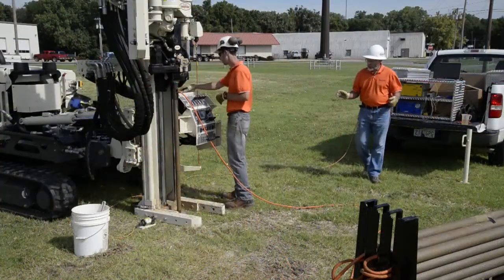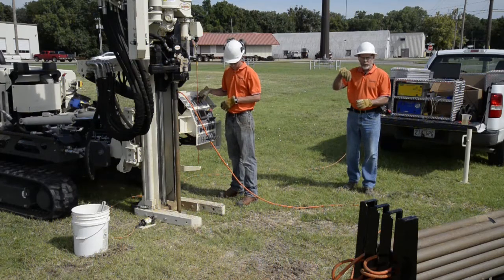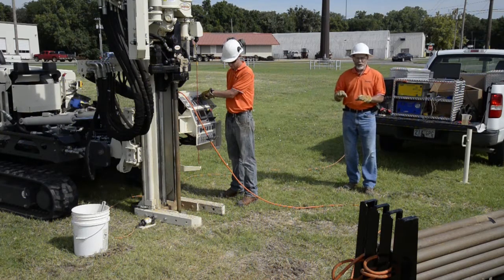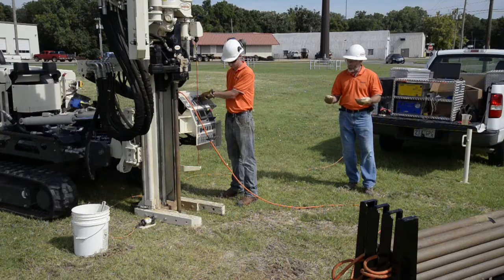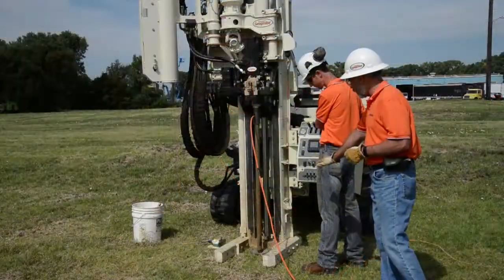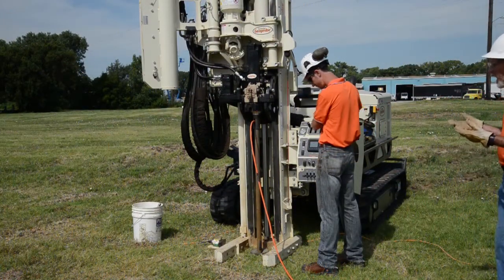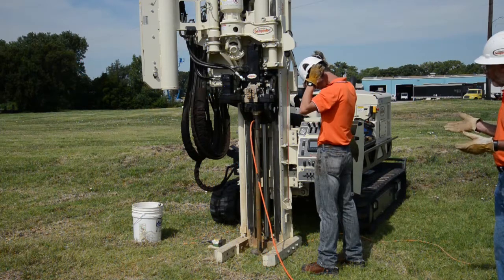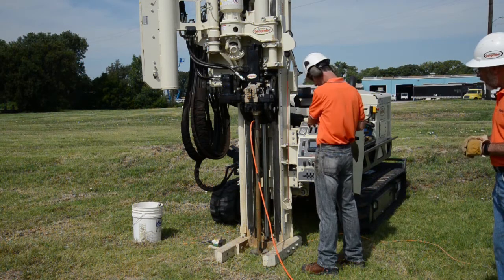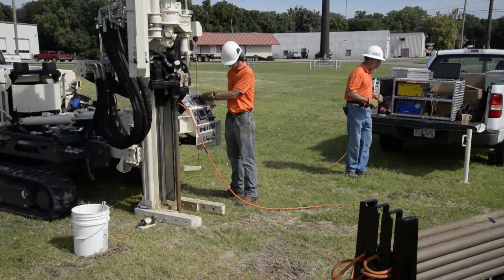It's really helpful to level up the probe, make sure the probe is plumb, so it's much easier driving, and then it's also much easier recovering the tools. And you'll notice we have the rod wiper on the ground here, and we'll use that when we pull the tools out to remove mud and goo from the probe rods, so the tools come out kind of clean. We don't have a lot of cleanup work to do. The rod wiper is really nice.